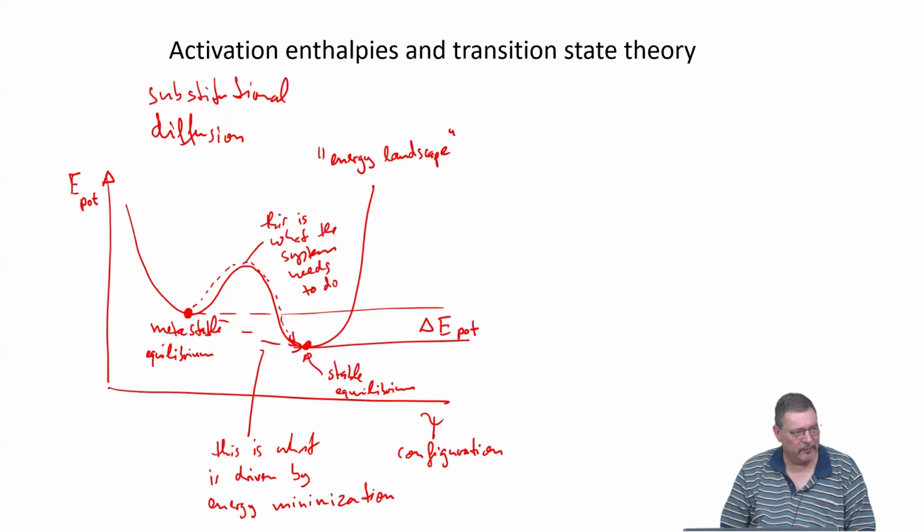Because the term driving force is technically incorrect, since it's not a force, it's an energy difference. This comes from the description of non-equilibrium thermodynamics, where forces and fields are affecting the direction of a thermodynamic system to develop from non-equilibrium towards more close to equilibrium conditions. But people have adopted this, so it's called the driving force. So the system wants to gain energy, and this is why it is developing in a certain direction.